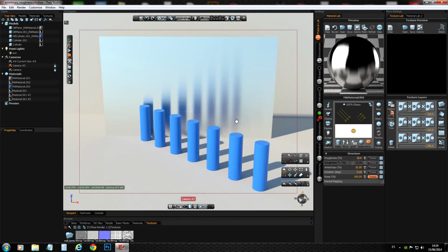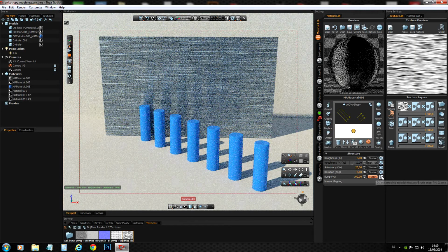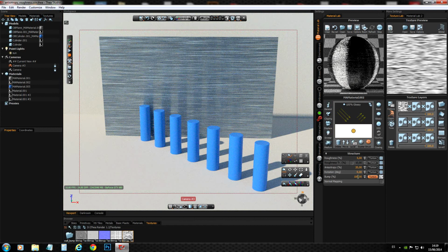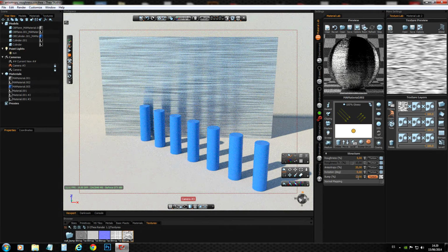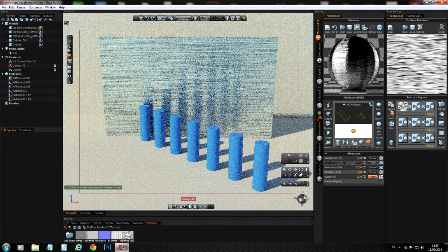Now, often you will see in brushed metals that there are visible scratches, because right now here you don't see any visible scratches. It's very smooth, everything. And there are several ways you can add this detail to the material. Now, one way is using, again, the scratch map. Now it's way too strong, so let's lower this value, let's say to 10, or even lower, something like 5.